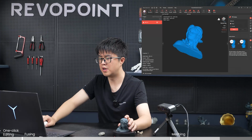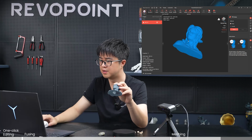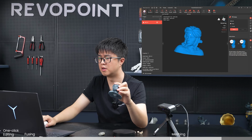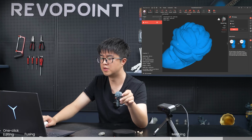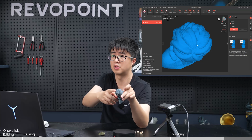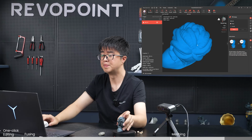Look, this area does not look really like what it is in the 3D model, right? This area here and this area here. And also there are a lot of holes we see on the top of the head, especially the hair part. Look, these are the parts where we used the fill hole function, and it lost all the detail because it cannot anticipate what is in the original 3D model.